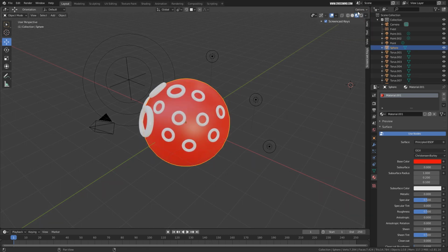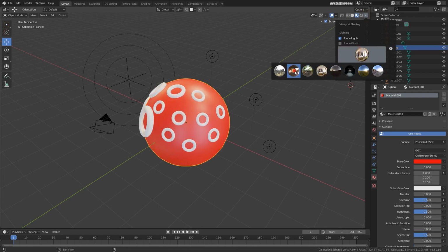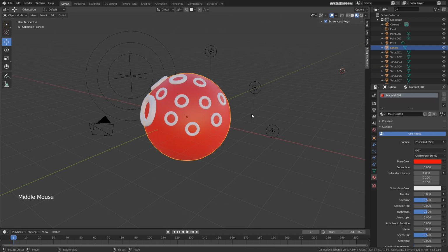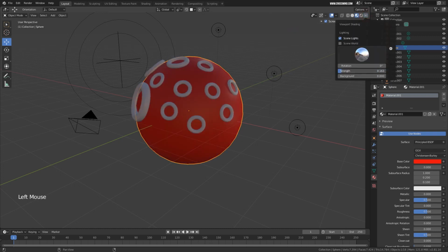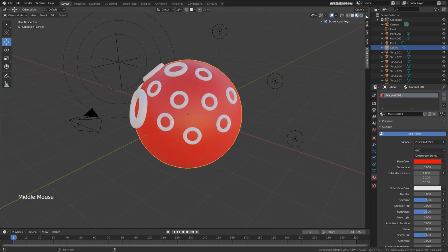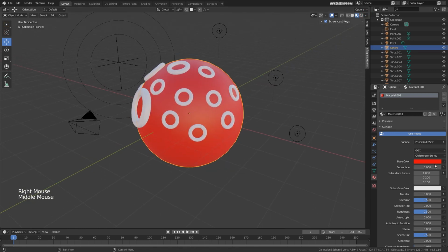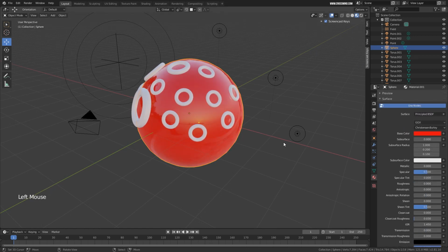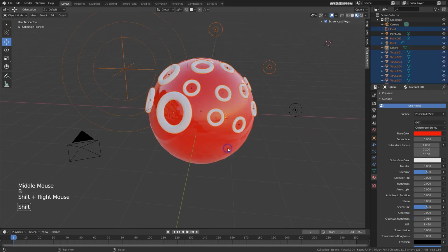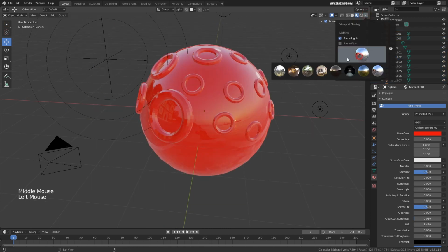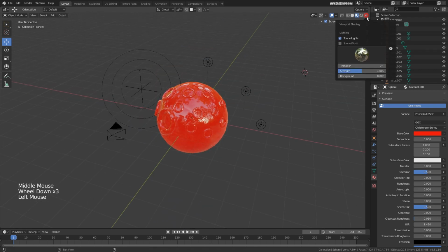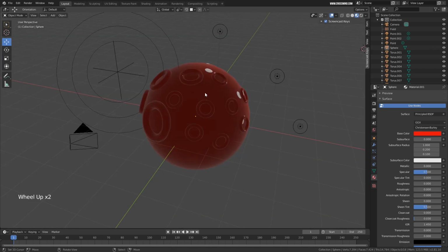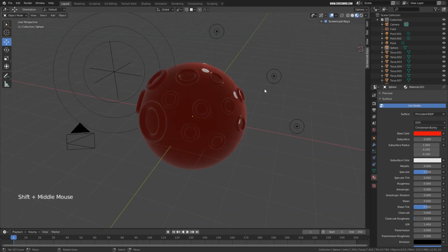You can go to the material preview and choose which kind of HDR you want to use in the background. When you are shading, you might want to preview the object with different settings, so you can use these HDRs, and you can increase or decrease the strength. Also you can rotate your HDR in the background. This is just for clearing this option. I don't want you to get into any details of material at this moment. So you can change your HDR from here and see the preview of your object, and these options are whether you want to use the scene lights or not, or scene HDR or not. Right now we don't have any HDR in the scene, that is why it's showing black in the background.